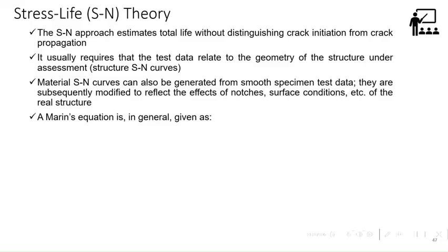So Marin is the person who found this effect of parameters on the SN curve: Se, that is the actual endurance limit of the component, will be your S'e, which is what is generated through testing. Whether you do axial, bending or torsion, whatever the testing, it is done on a specimen of the given material. Whether you use a dog-bone specimen or a round specimen or whatever it may be,